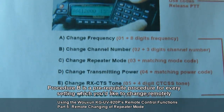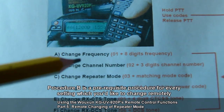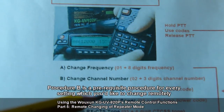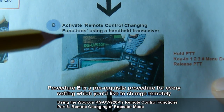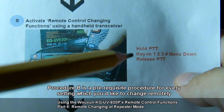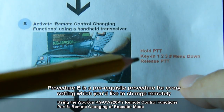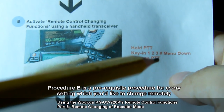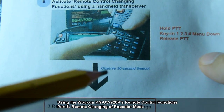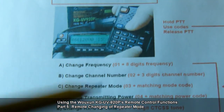Take note that for every setting that you'd like to change remotely, such as changing frequency, channel number, repeater mode, etc., you must first do procedure B. Procedure B is simply holding your HT controller's PTT, keying in 1, 2, 3, pound, menu, down, and releasing the PTT, and then within 30 seconds you do any of these.